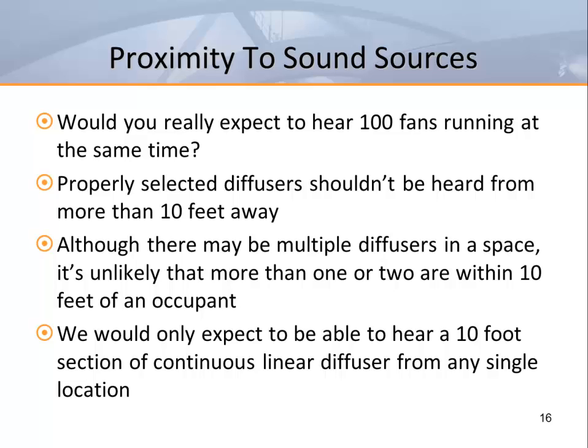It's important to understand that in large spaces with multiple diffusers, possibly high in the air, we don't need to concern ourselves with the additive effect of multiple sound sources. In these spaces, the distances are too great, and the room volume also acts to absorb what little sound they may create. For the same reason, we say that it shouldn't be possible to hear any more than a 10-foot section of continuous slot diffuser.